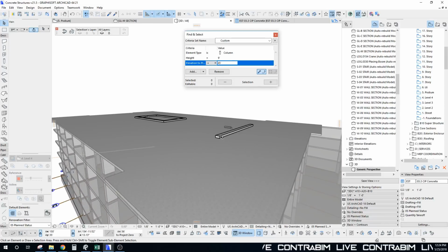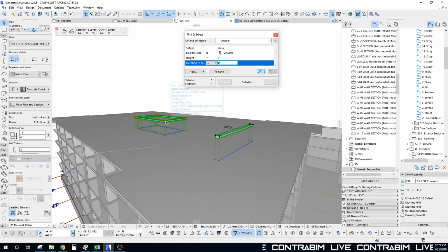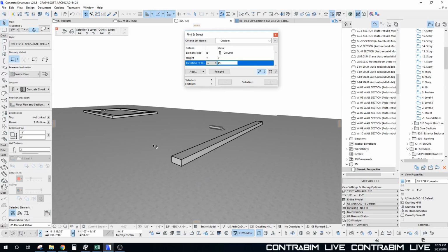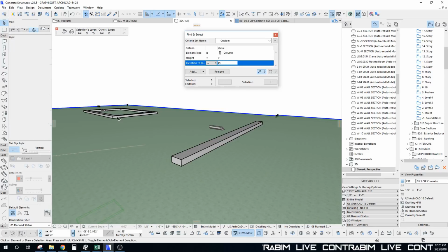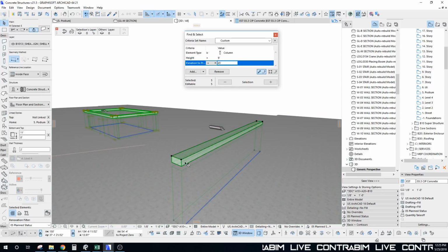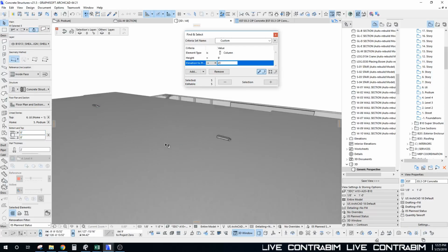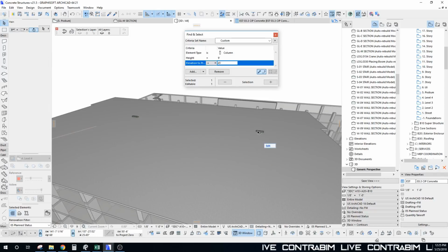So I can also see my walls poking through here. So first thing, I just want to make sure that I'm at the right elevation with my slab before I do a lot of adjustments. So height and home offset. So okay, we're good there. These probably don't have a top link, so I need to change them to that. And we're going to go -8. Actually, no, we're just going to leave 0. There we are.